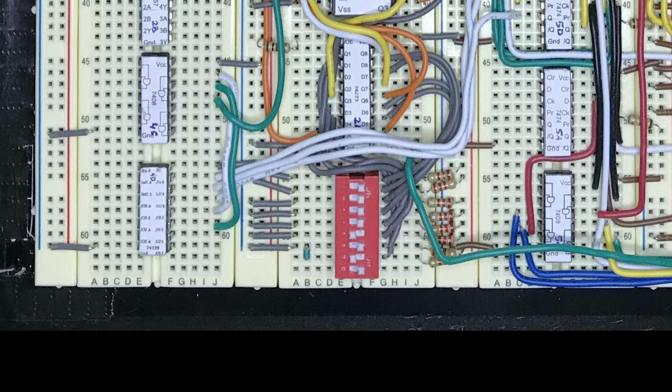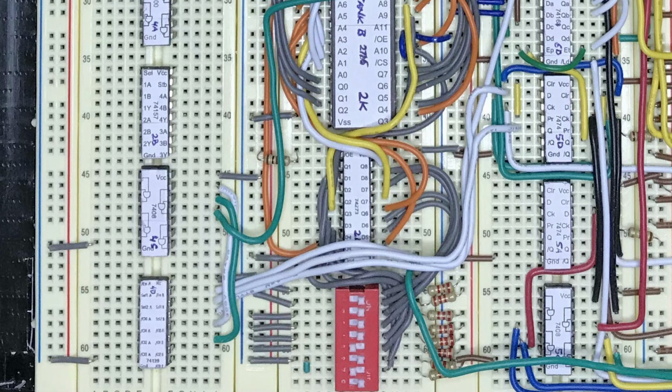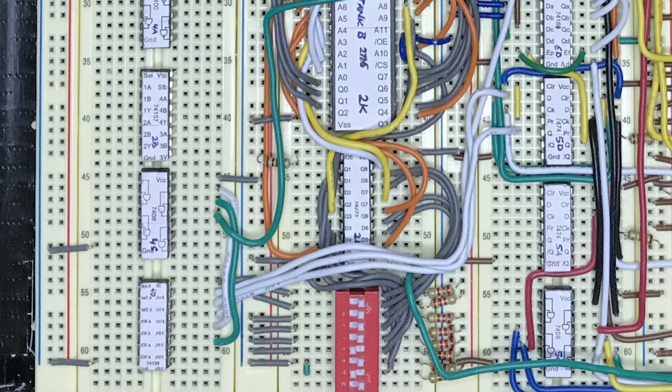In terms of connections, we have the dip switch, each switch connected to ground on the left side, and on the right side all connected to 5 volts through a 2.2k resistor. It doesn't matter too much, around 1k is fine. Then on the right hand side, all dips are connected through the grey wires to the 74LS273 D inputs. For any chips that show RP on the schematic, these pins are tied to a pull-up resistor that's typically a 1k resistor between the pin and the 5 volt rail.